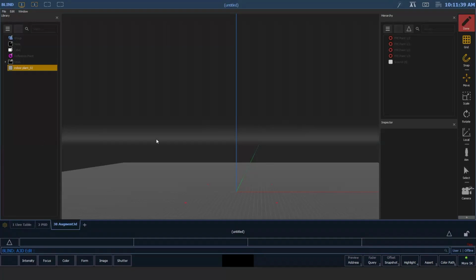In a theater space, we'll say a proscenium, a best practice might be to have your X origin be your center line, your Y origin could be the upstage side of your plaster line, and your Z origin would be the height of your stage, of your deck. That way, when you're placing objects, which we'll do shortly, you can say, oh, I know that it's 3 feet left of center, 9 feet upstage of plaster line, and its trim is 20 feet.